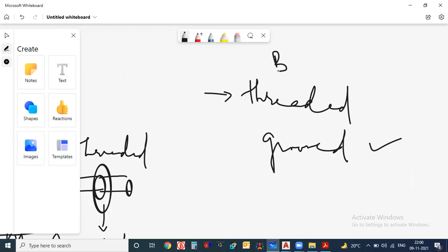But if anyone is using butt weld fittings, their cost is very, very less, because in butt welding we don't have to do anything; we just have to join two pieces and do some welding here. So remember, these fittings are joined either by solvent welding, or by arc welding using electrical machines, anything which is available with the contractors, mostly electric arc welding.